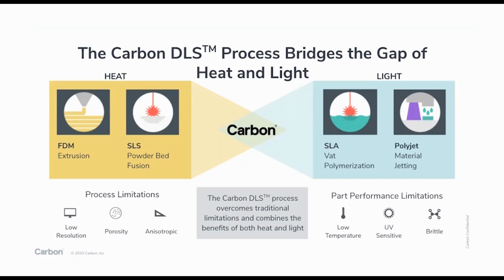The resolution is only moderate because of solidifying liquid on top of solid or consolidating solid particles with a thin liquid film or softened film. You get high anisotropy in the Z versus XY direction. And in the case of SLS, you get high porosity. But these materials have their place and their use.